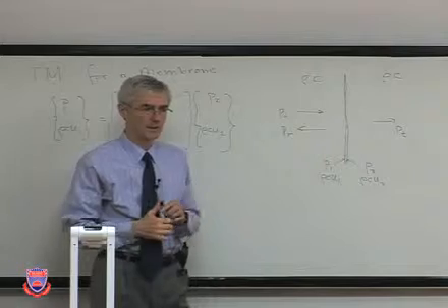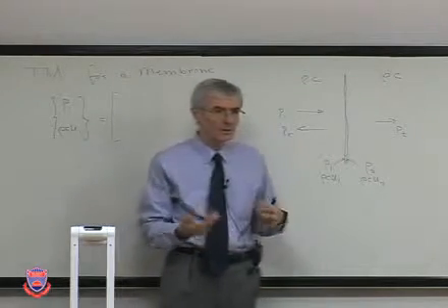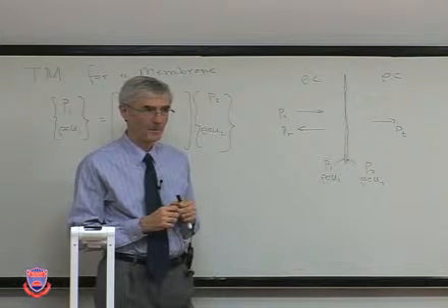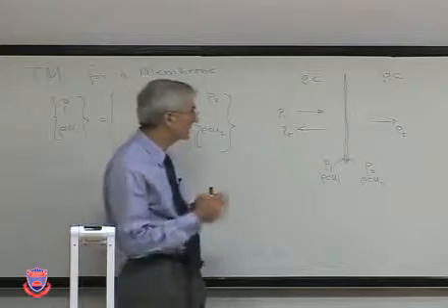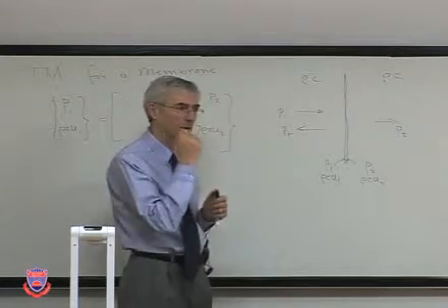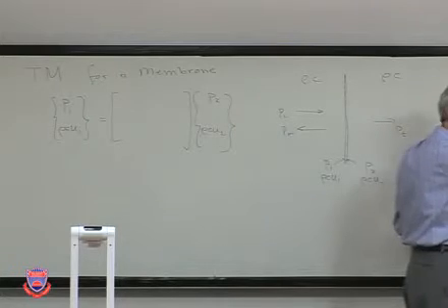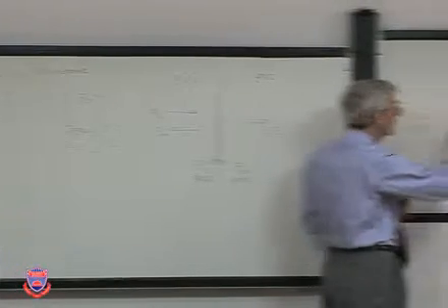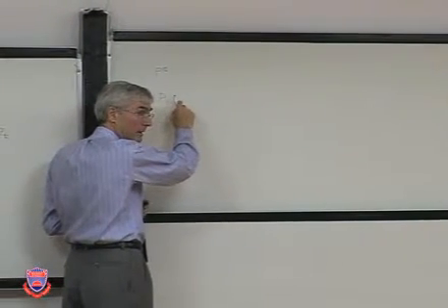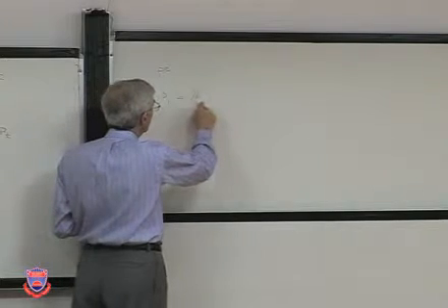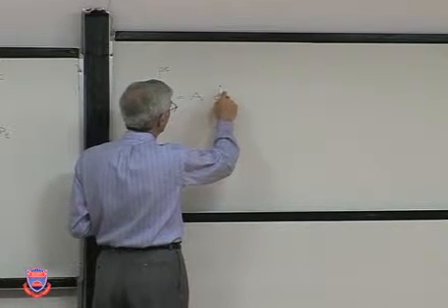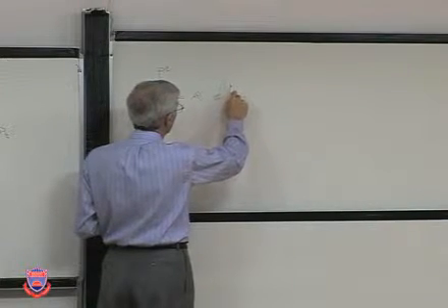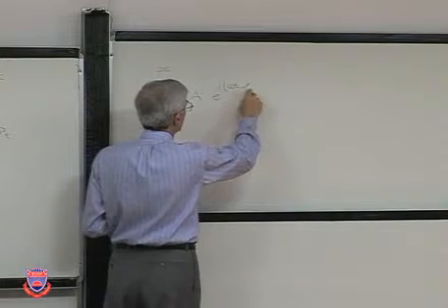What do we know about the system? We have to write down something. We can write the pressure distribution. Okay, tell me, what is the pressure distribution? I'm going to write it over here. P1 equals P equals what? A constant A, then e to the power i(omega t minus kx). Okay.